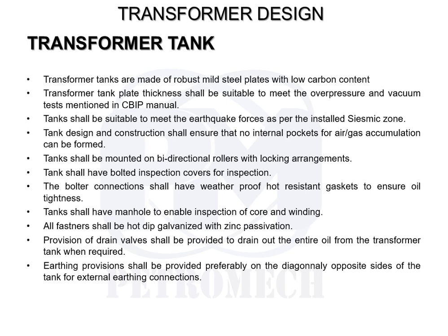All fasteners have to be hot dip galvanized with zinc passivation for corrosion prevention. A drain valve has to be provided to drain out the entire oil from the transformer if required in case of eventuality. Earthing provision shall be provided preferably on diagonally opposite sides of the tank for the purchaser's external earthing connections.